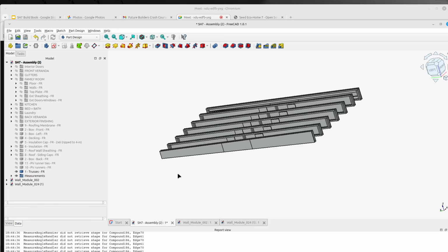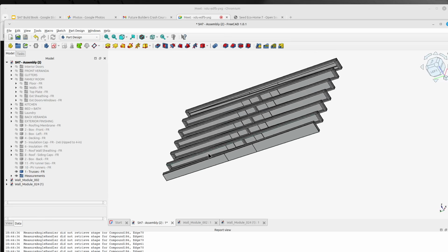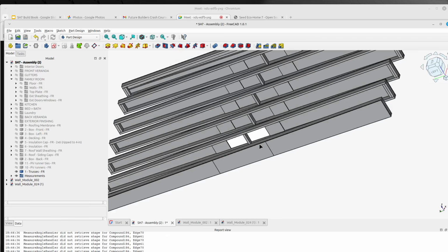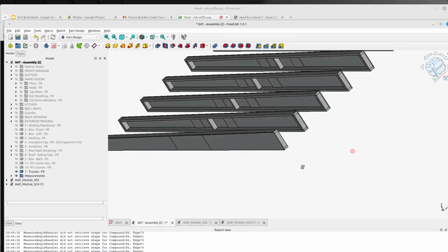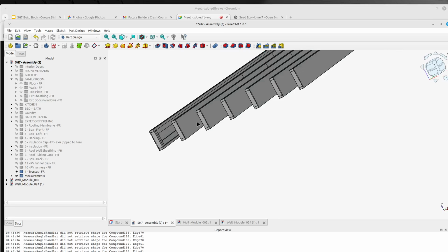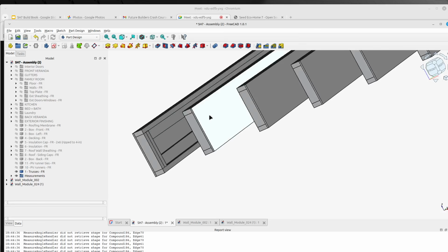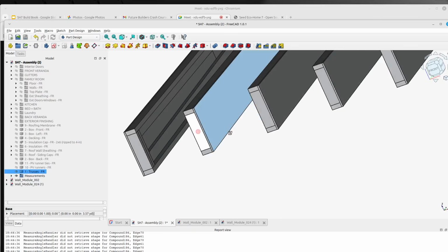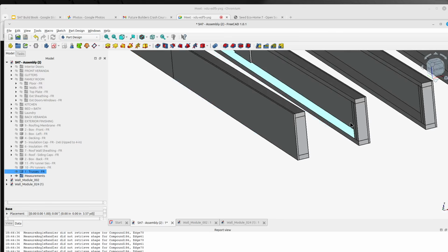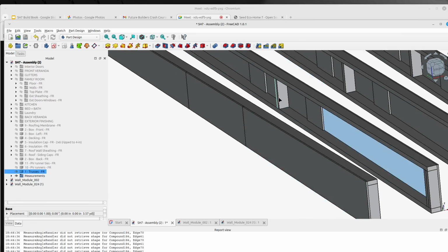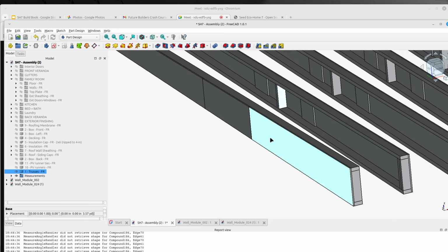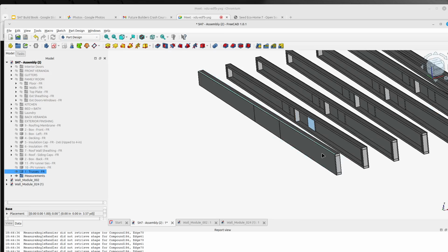You can't get it. I haven't seen a tapered truss, but what you've got is top and bottom cords, 24-inch centers, 50 pounds per square foot load capacity. That's how they look. So this is OSB on the one side, and this is all 2x4s. There's a middle vertical 2x4. The rest is OSB, 8 foot, 8 foot, and 4 foot section in the middle. There's bonding plates between the sections of standard OSB, and that's how they look.